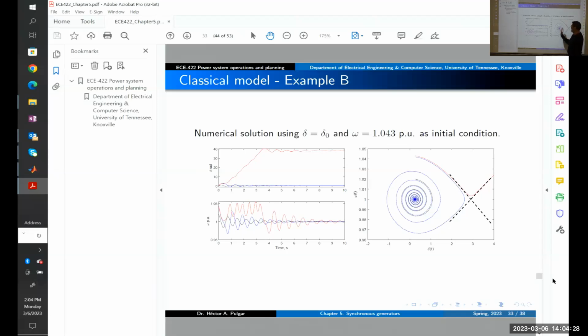Yeah, we don't have any short circuit. We haven't talked about short circuit yet, right? We're just playing with the initial condition, but we're going to have very large current. What I'm going to ask you to do with the code is get the magnitude of that current, and also get the electrical power for that case when the angle goes into that excursion. Yeah. What we're going to see, do you think we may have negative electrical power coming out of the generator?